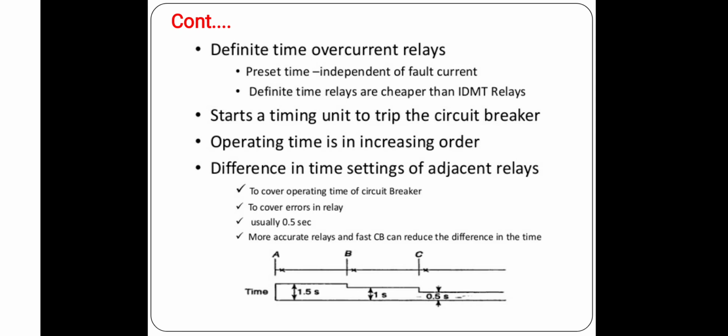But on the other side, this scheme takes the longest time in clearing the heaviest fault, which is undesirable because the heaviest fault is the most destructive for the equipment used in the power system or distribution system.